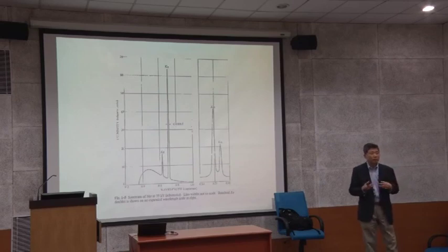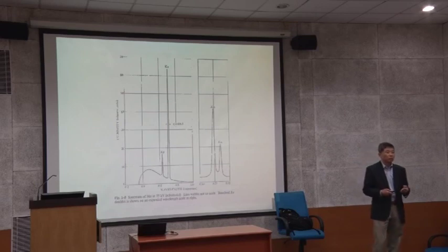For most thin films, the crystalline quality is very good, and your diffraction condition is met very easily by all the grains you have. So even though you compromise the intensity, you still get very strong intensity from the detector. But with a powder diffractometer, powder has a lot of randomly oriented grains, and only a very small fraction contributes to diffraction. That's why a lot of powder diffraction needs a large-area line focus, and sometimes people don't care that much about resolution, so you don't need a monochromator.